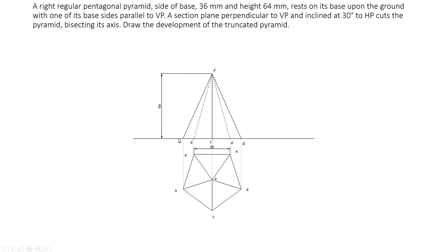Now the outermost triangle should be dark line, and here you can see two dotted lines, because these two lines will be invisible. So to find the invisible lines in front view, you consider extreme left and right points. So extreme left and right points are B and D. So whatever points are coming above that, that is A and E, all the lines to those A and E will be dotted lines. So you have to use dotted lines to represent those two lines, O dash A dash and O dash E dash, because those lines are invisible in front view. So this is the front view and this is the top view of the initial position.